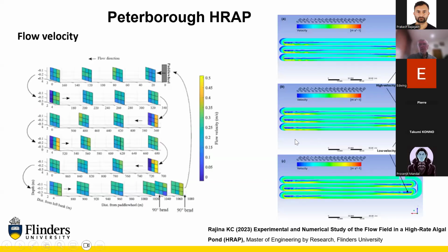Okay. So the first thing that we did, we were saying this is a 3D characterization. When you're looking at doing flow measurements in these systems, you take the left bank as when you're looking down the direction of flow. So here, the left bank is this bank. Here, the left bank is this bank on this side of the pond. So you have to orientate yourself as being the left bank looking in the direction of flow.